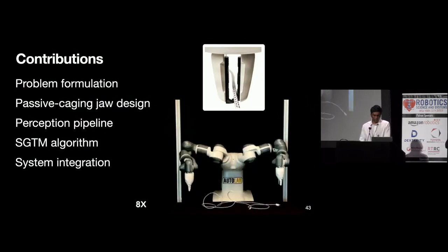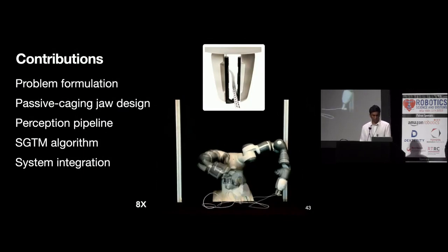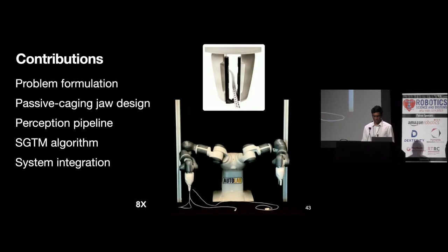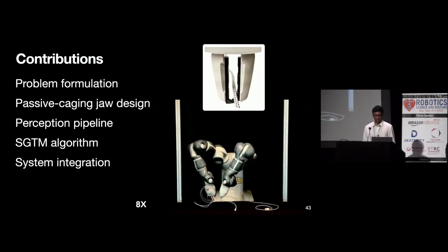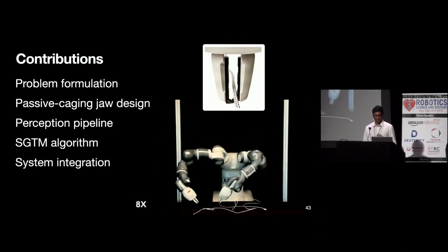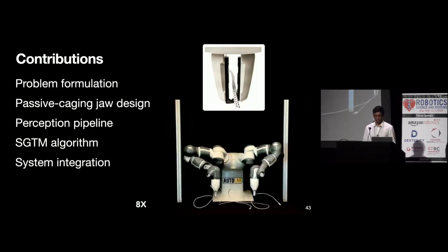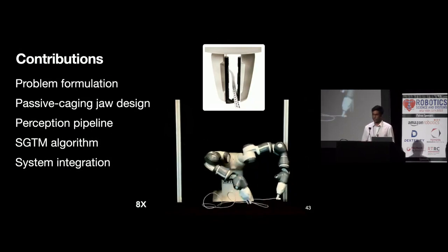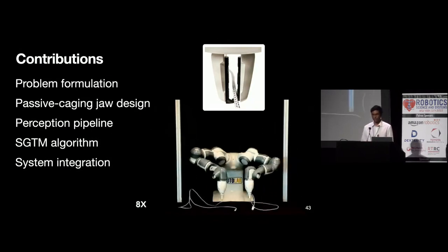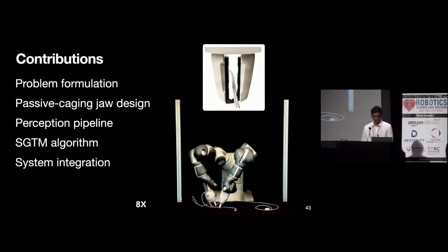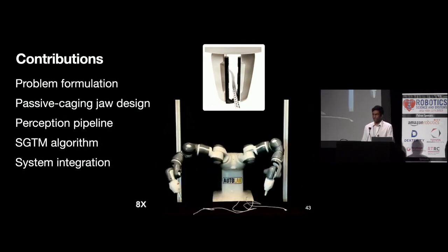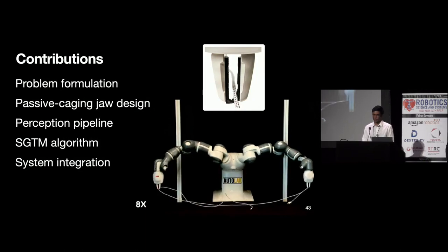And finally, our contributions include a problem formulation for the untangling long cables problem, a dual mode gripper design that critically allows for sliding and pinching actions, and we also leverage the unique capabilities of these grippers and combine them with a perception pipeline into the SGTM algorithm and present a unified, integrated system that is modular and capable of untangling long cables up to 3 meters in length.